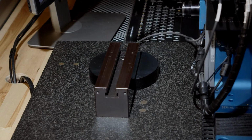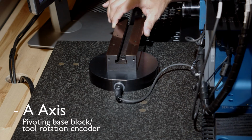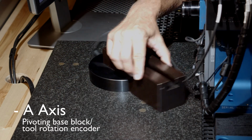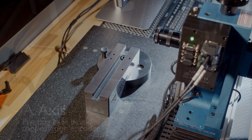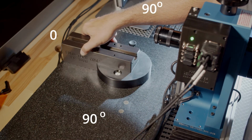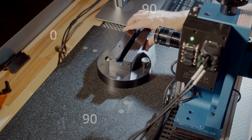400 models have an A-axis encoder. This is a magnetic encoder which reads and displays the position of the pivoting base block of the 400 in degrees and minutes and gives that information to the software, which allows it to be reflected on reports. This feature allows the user to be more consistent when setting up for repeat tool inspections. PG1000 200 doesn't have an encoder for the base block, so base block position is therefore not displayed on the software or on reports. Instead, a protractor decal and a manual index plunger with fixed locations at -90 degrees, 0 degrees, and 90 degrees is provided for location reference.